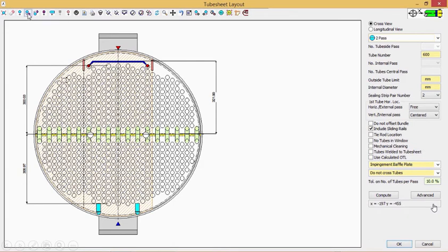We can change some of the tubes to tie rods by the option that is available, change tubes to tie rods. We will perform similar operation for a few other tubes. As you can see here, the software has already removed the corresponding end of the U tube from the other side. So we change some of the tubes to tie rods. It's very easily done by click of a button. Now if you want to change the tie rod back to tube, that option is available too. Observe the lower tie rod is changed back to tubes.